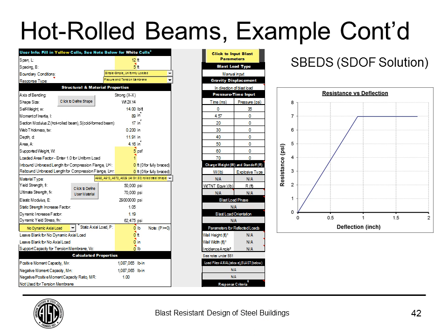Now let's compare that to the SBEAT solution, or any single degree of freedom approach. In SBEAT, it does the calculation of the single degree of freedom parameters for you. So we would enter here the span, 12. I know the picture is a little bit small, but hopefully you can see it better in your notes. We enter the spacing, which is 5 feet on center. It's a simple beam. We have flexure, and then we enter the beam that we're analyzing right here, and it uses that to calculate the single degree of freedom parameters, and it develops a resistance function like this here.